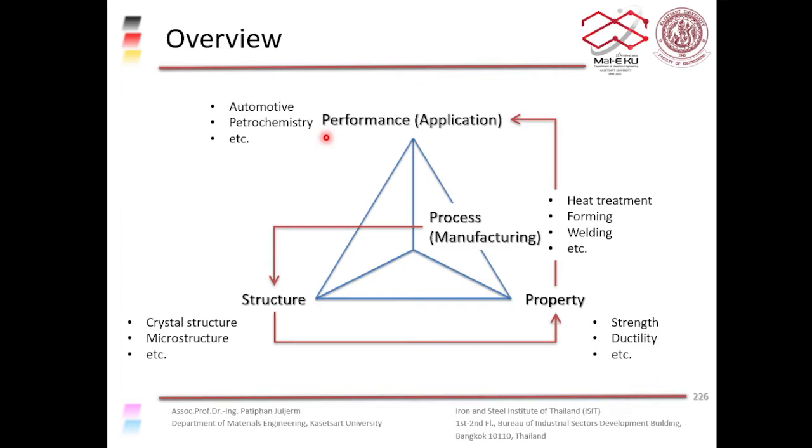At the same time, if we have a lot of grain boundaries, you have a lot of creep. So we have to think of a way that we can manufacture a turbine blade without having any grain boundaries. In other words, you need to produce a single crystal turbine blade, right? So that's our manufacturing process.